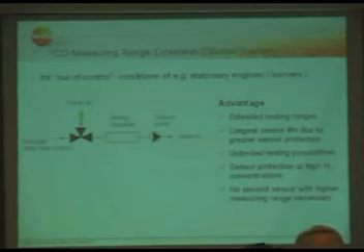But you know, the H2 reading in your display is just an indicator. The accuracy is plus minus 50%. It's not very accurate, but it's as accurate as needed for the compensation taking place. This is just information because we got a lot of requests: okay, we have the H2 reading in the display, it's very high, can this be? Usually the H2 reading should not be used as a parameter to be measured. It's just for the internal compensation. But you can show it.